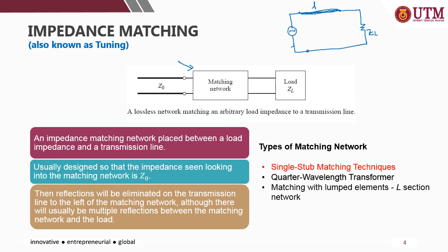So as we have known, there will be a standing wave for the signal within the transmission line due to the reflection at the inner surface of the transmission line. Therefore, there could be power losses during the transmission. So to minimize or avoid reflection or power loss, a matching network is introduced in between the transmission line and the load.